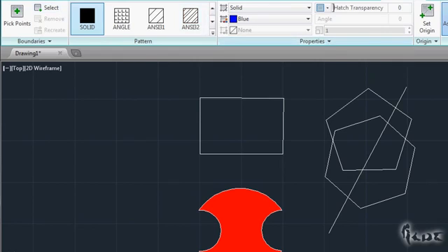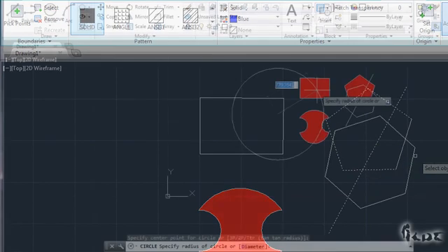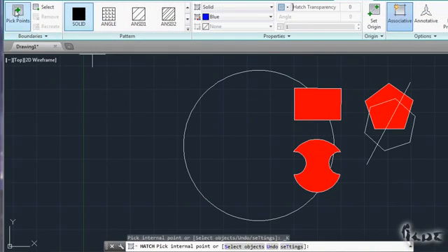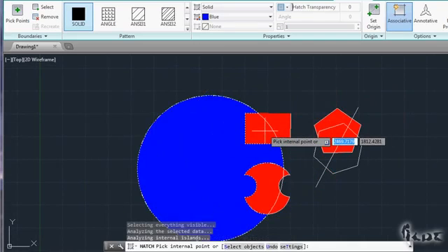Otherwise, you can choose Select. This does not require an enclosed area, but objects selected that together create the enclosed area to fill with a pattern. The hatch will not be created until an enclosed space is revealed with the points selected. If you are adding a hatch pattern, keep in mind that the filling stops at the first boundary. If you want to expand the filling, you have to click over these boundaries.